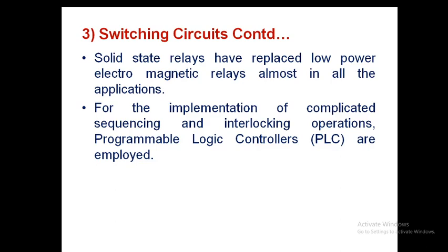Solid state relays have replaced low power electromagnetic relays almost in all applications. By using these solid state switches, we can control smoothly. The only thing is that you need to give the proper switching sequence from the switching control circuit.